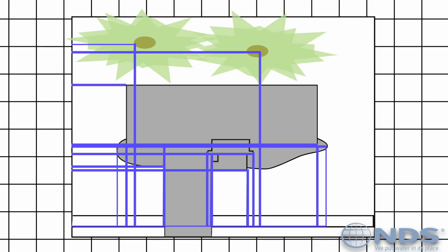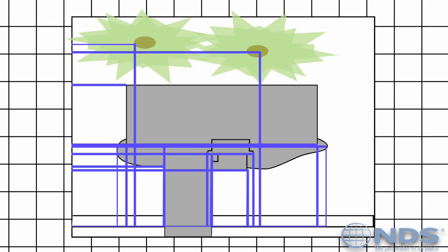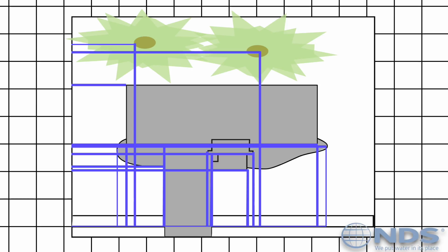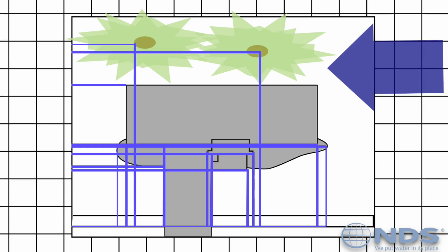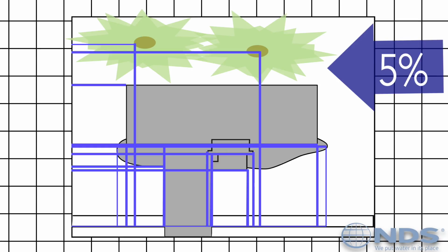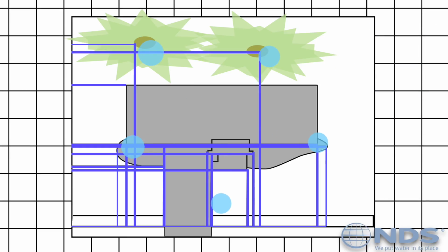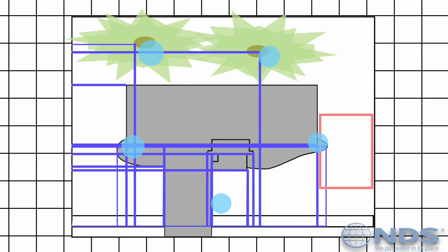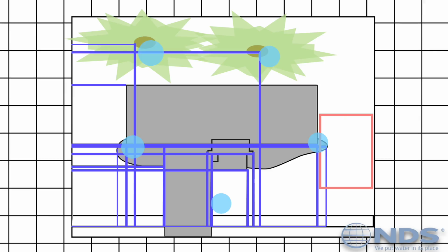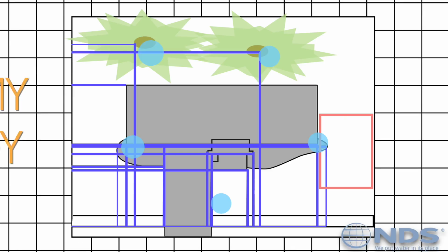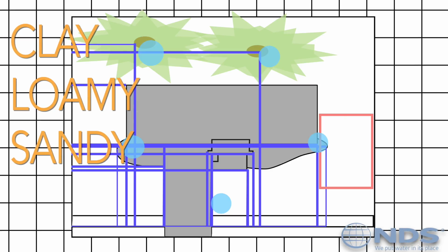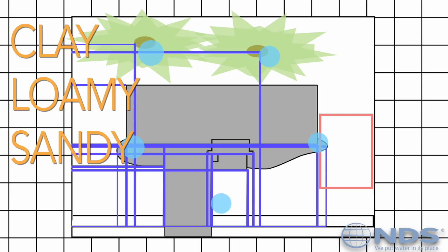In addition to the basic site features, note all of the items we discussed before. Slopes on the property with arrows indicating where the water flows, and identify the percent of grades for all major slopes. Sources of incoming runoff. The dimensions of the area on the property that are causing runoff to the problem areas. Soil types for all areas, as these impact the runoff rates.